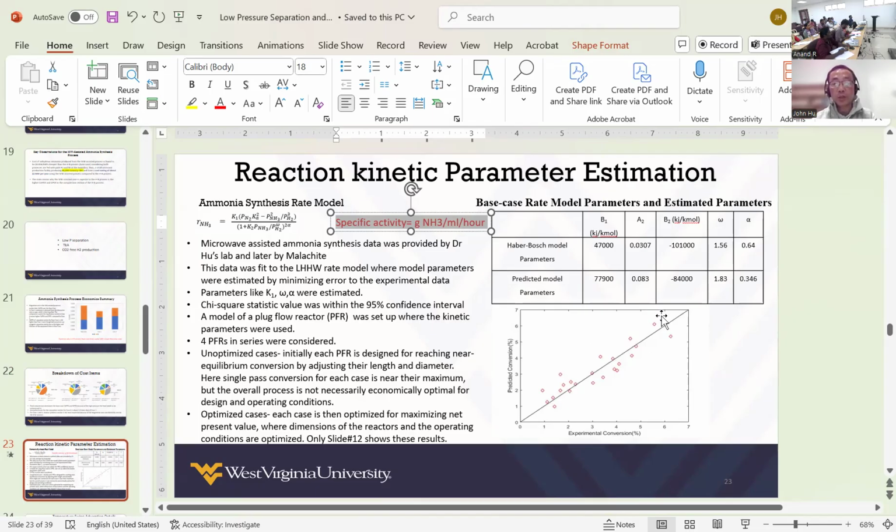linear regression. Other than just one data point from small, you project the large, but you have to do a lot of kinetic study. Anyway, this is in the real engineering world how you size the reactor, because you have to develop the rate equation.